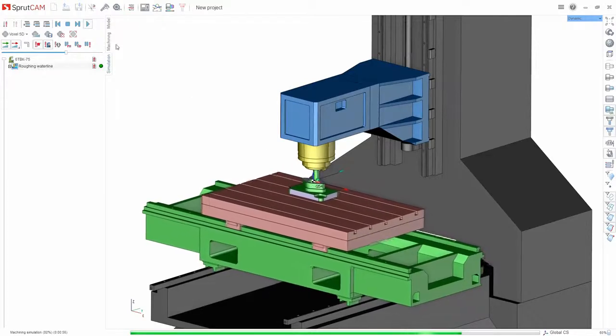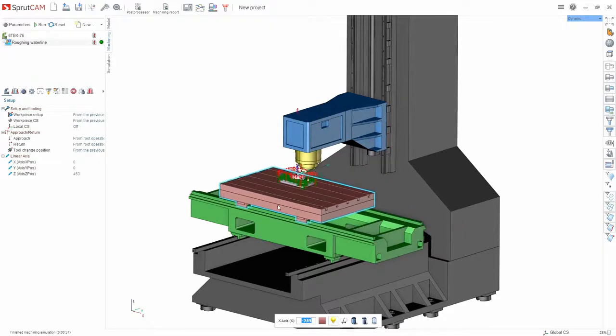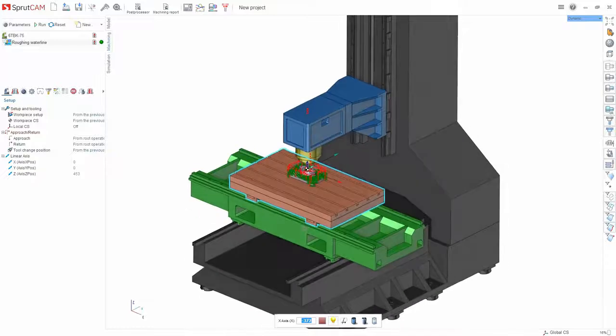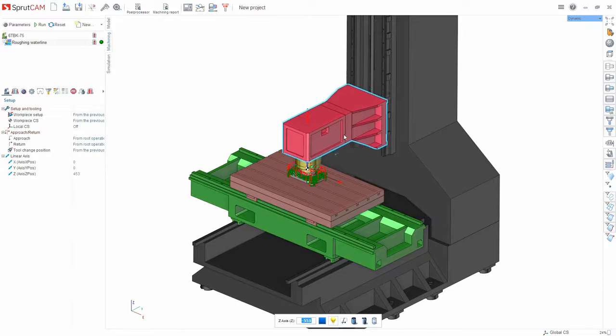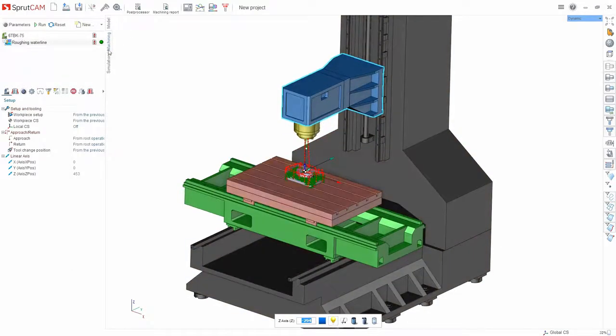Return to Machining tab. Here we see that there are borders registered in the scheme. Now we can observe that we move the table along x-axis and at some point it starts to turn red. That means that we go beyond the limit switches of the circuit. Each machine has its own limits on the working parts. As you can see along z-axis, it also turns red at a certain value. We can avoid this error. Here we see an exclamation mark. This can always be corrected. For example, to make setting of the part higher means to add some kind of fixture.